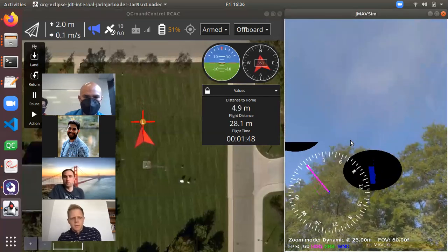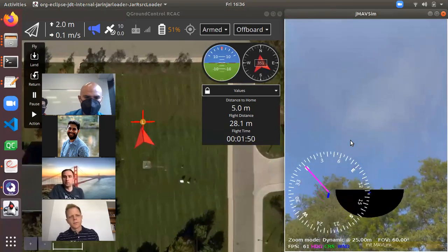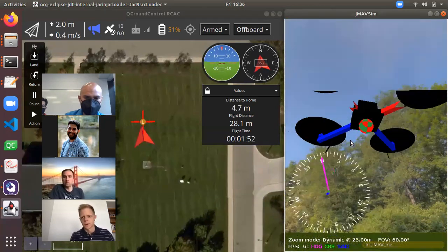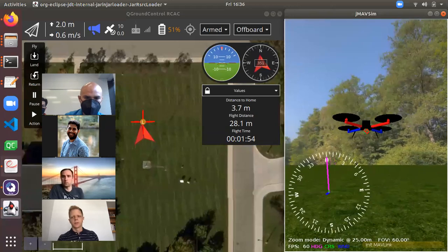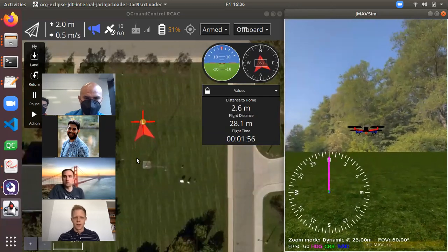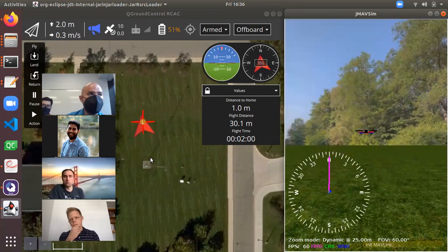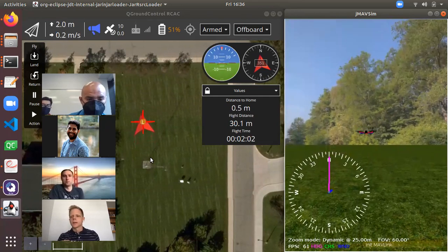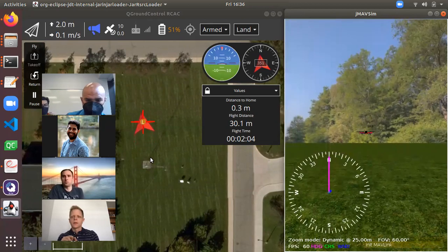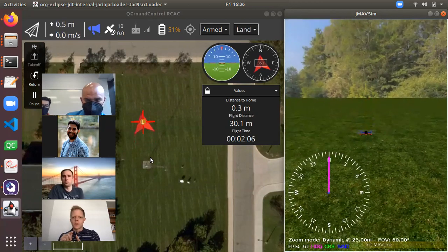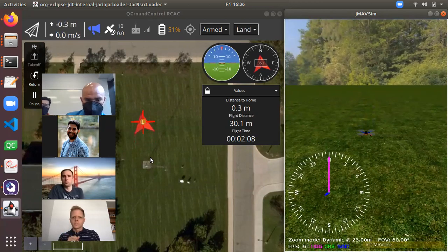So by changing that filter, aren't you effectively changing the response of the position and the velocity control? No, that filter is not applied to the controller. That filter is applied to the trajectory generator. So the trajectory becomes slower.